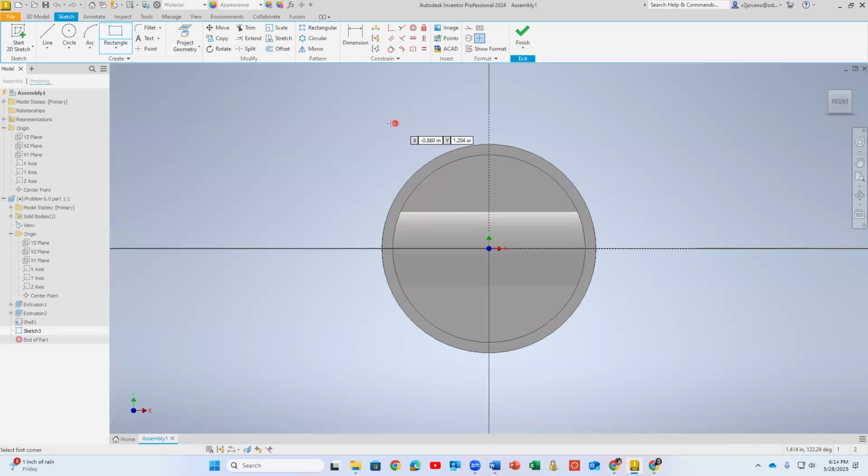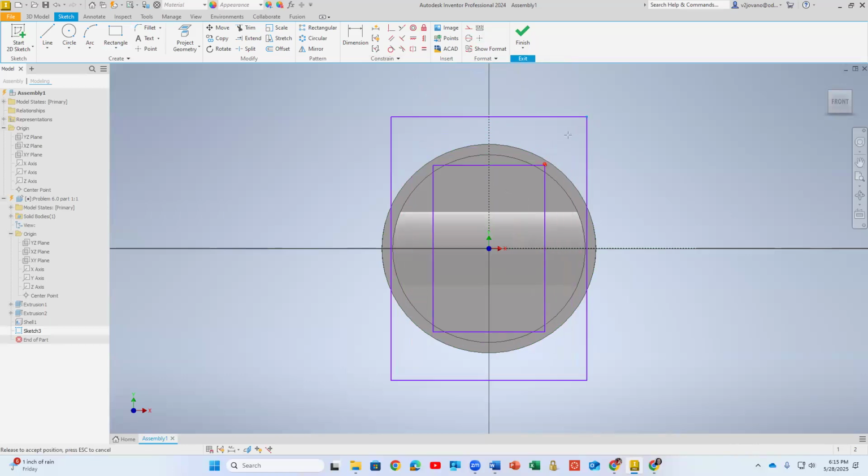You see, I can make it anywhere like this. I want to make it not perfect because I want to introduce you to one other constraint. It's called symmetric. I have a left line, a right line, and this one in the middle. I use symmetry and say left, right, and the middle, please align so you're symmetric. Then I escape, start fresh, and say up, below, and what's in the middle. Now if I escape and go to the corner, you see it's perfectly symmetric.